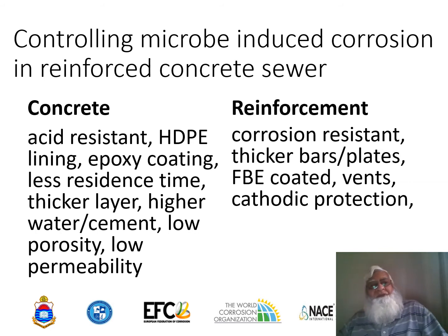Then higher water cement ratio. If you have a high water cement ratio, it means there is more water in the concrete, which can dilute the effect of the acid gases formed from the microbes. Then porosity: if it is low porosity and low permeability, right, it can prevent the gases from entering into the concrete.